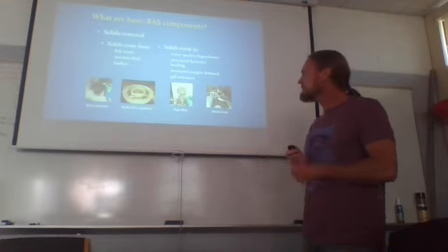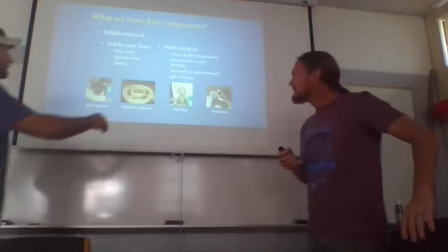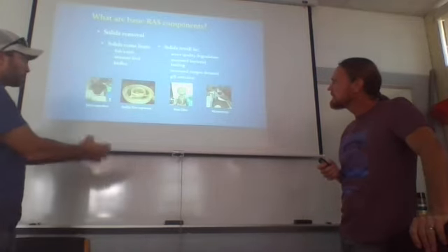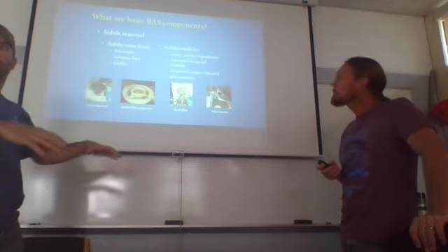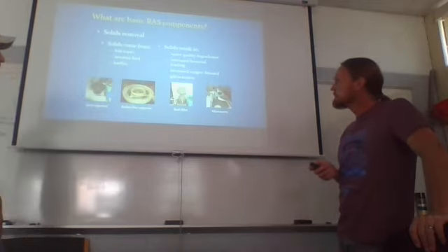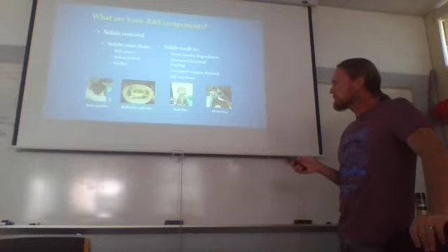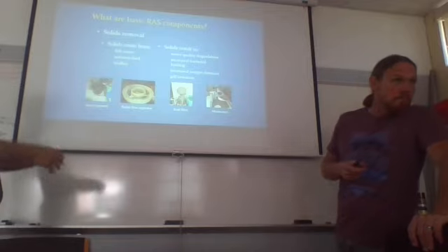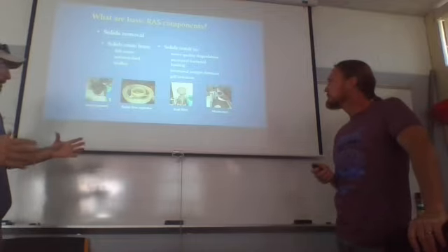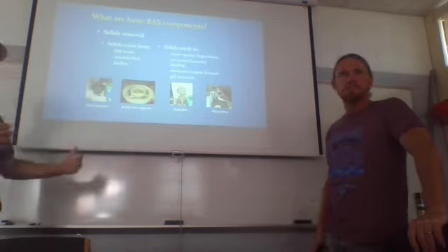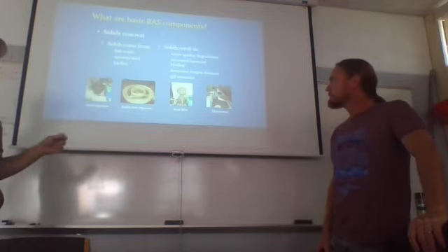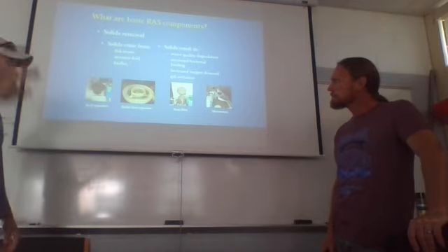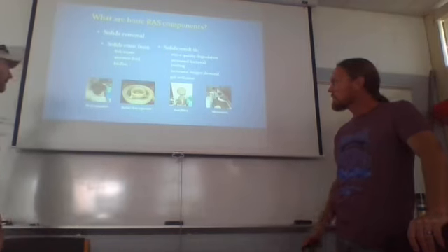The radial flow separator I've never used. How does this work, Dave? So the water flows in the center and goes down, and then goes into a wider container, so it slows down on the way up, and basically the solids fall out on the bottom, and then you purge them out. So they just work as baffles then? Same idea. It's basically one round baffle, and the diameter of it is controlled by your flow rate. It's got to be going slow enough that whatever the particle is, it can settle out to the bottom, depending on what it is.